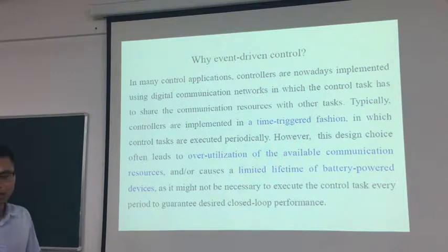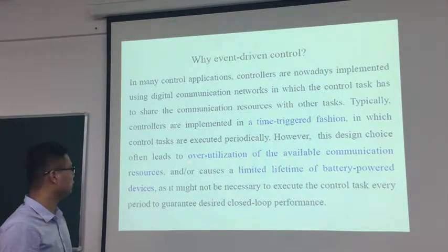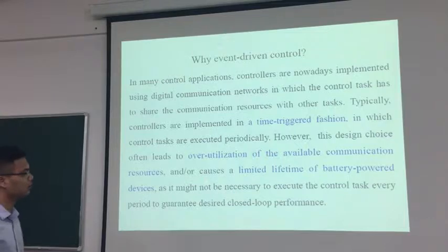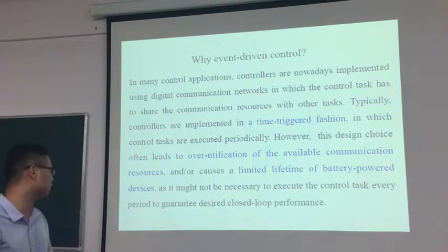Okay, next I will try to answer the second question. Why event-driven control? In many control applications, controllers are nowadays implemented using digital communication networks, in which the control task has to serve the communication resources. As a consequence, if we use the time-triggered fashion, where the control tasks are updated periodically, this design would lead to overutilization of the available communication resources or cause a limited lifetime of battery-powered devices.